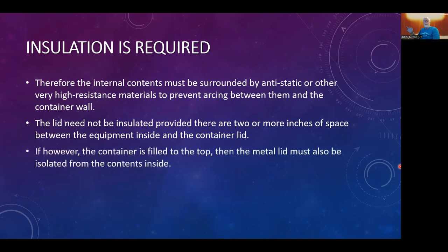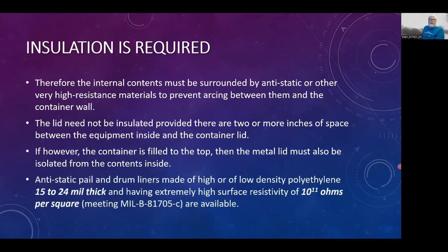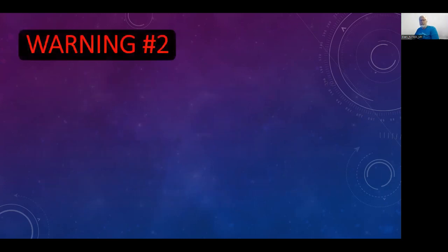If the container is filled to the top, then the metal lid must also be isolated from the contents. You can buy some really good quality 15 to 24 mil polyethylene material, having high resistance, 10 to the 11th ohms per square meter, I believe, meeting mil spec, and you can get that on the internet on Amazon or eBay.